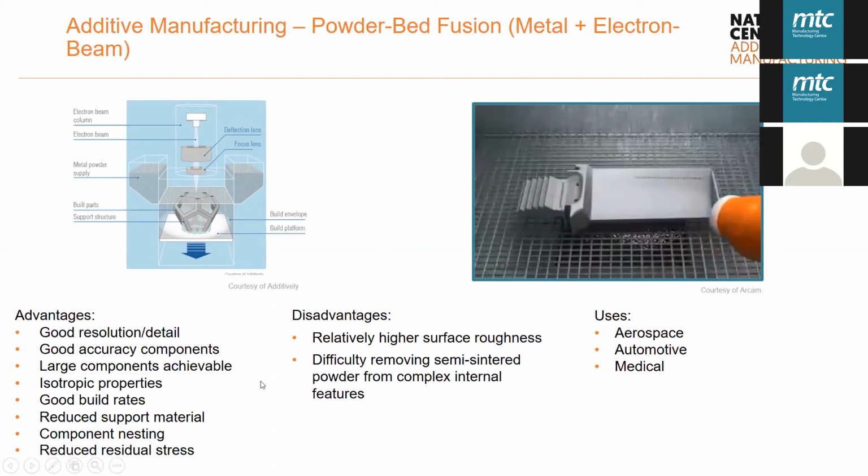Because the platform is heated, and there isn't that great of a temperature gradient during processing, you reduce your residual stresses and you don't really require a heat treatment step.